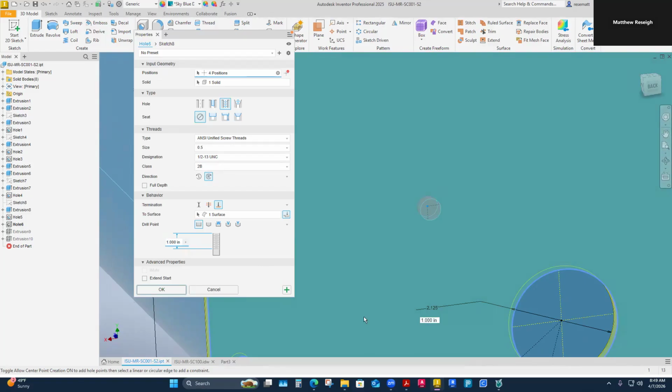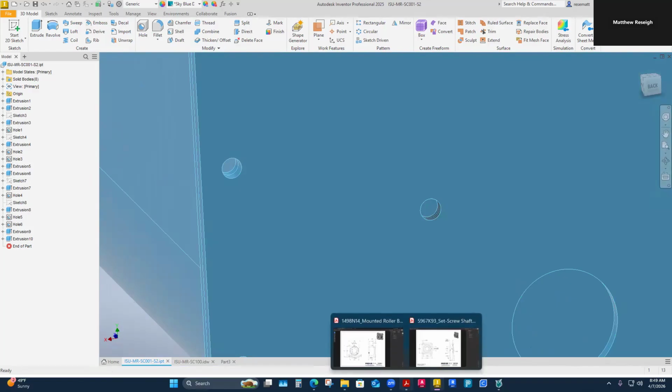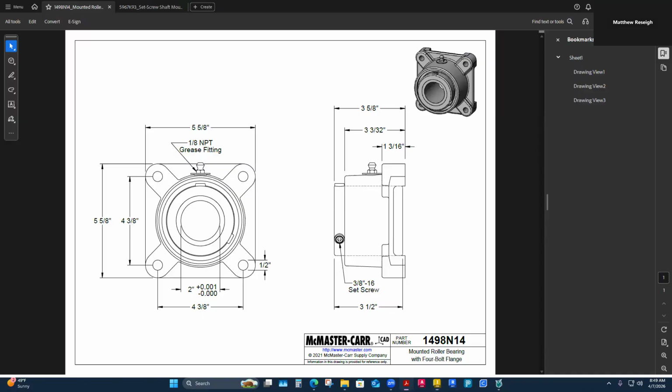What I'm kind of tripping out on a little bit is that I think that's going to be fine. Of course, I could always go back and change it later anyway. But I'm looking at my data here again with a new set of eyes. I haven't looked at this for a week or so, but I like my 7/16 to hold up this one. I'm undersized of this, but I'm not hugely undersized. 3/8 would be pretty sloppy. It's a 16th undersized, so it would have like a 32nd all the way around. It's almost 30 thousandths clearance.